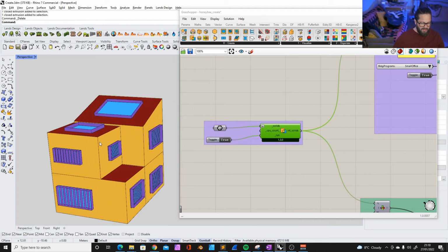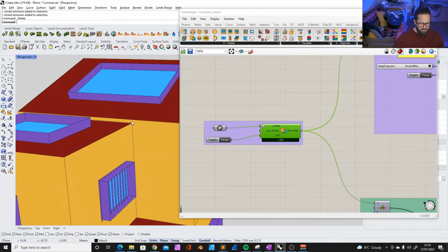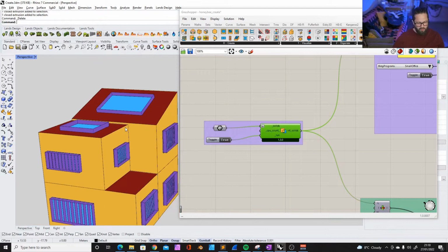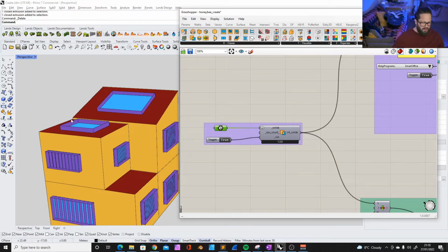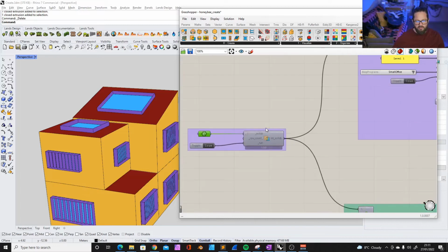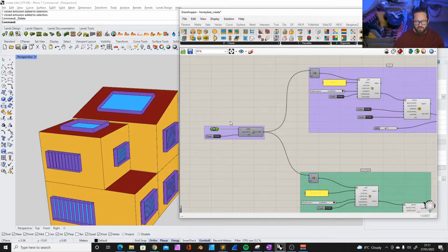In this case, the smaller room, and I made it deliberately not as tall as the other one, this tool recognizes that this room is touching that wall of the bigger volume in the back, and creates a subsurface on that wall of the larger volume, and cuts out a surface. That makes sure Honeybee knows there are two overlapping surfaces of the same size, and that is an interior wall. Otherwise, Honeybee would think it's an exterior wall, which is a big difference.